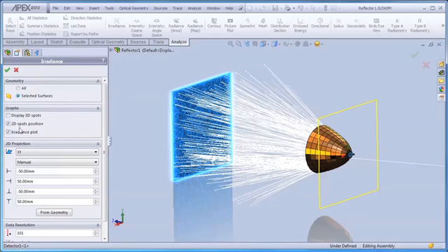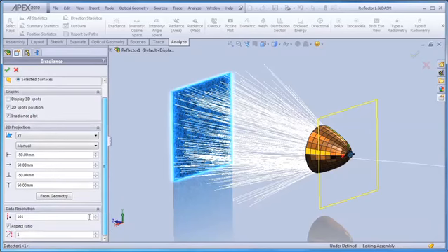We're going to print a 2D spots diagram, which is the locations of all ray intersections on the front of the detector surface, and we'll print a false color irradiance map. The geometry for our irradiance plot will be taken directly from the detector surface, but we can manually adjust the size of the plot if we wish, and we can also adjust the resolution and aspect ratio of the resulting plots.